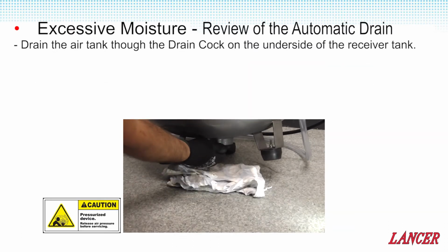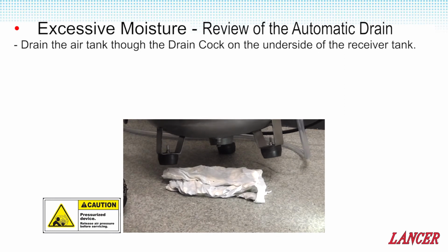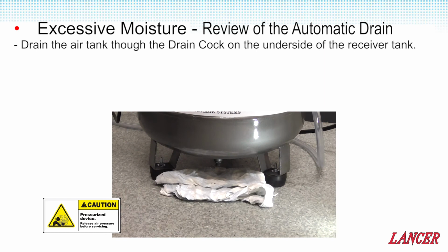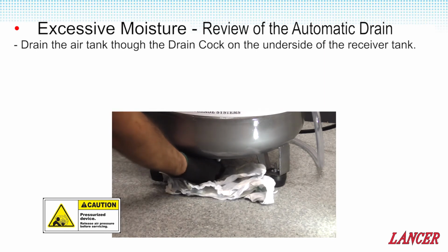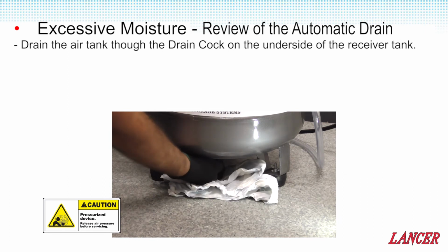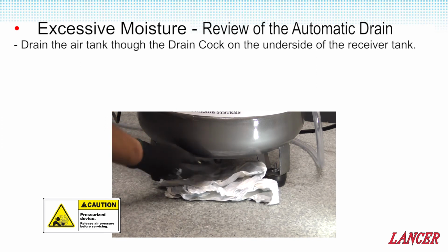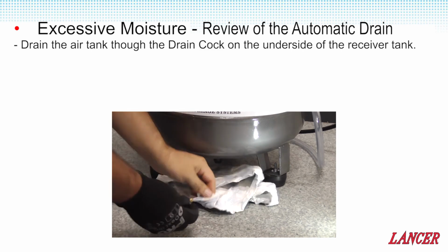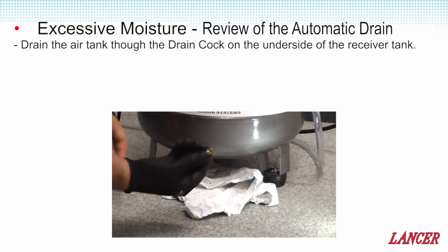With gloves and glasses on, loosen the drain cock to bleed the compressed air from the tank. When depressurized, remove, clean and replace. And just make sure that that's all clean, which it is. And just give it a little wipe with a bit of a rag. Make sure that's fine.